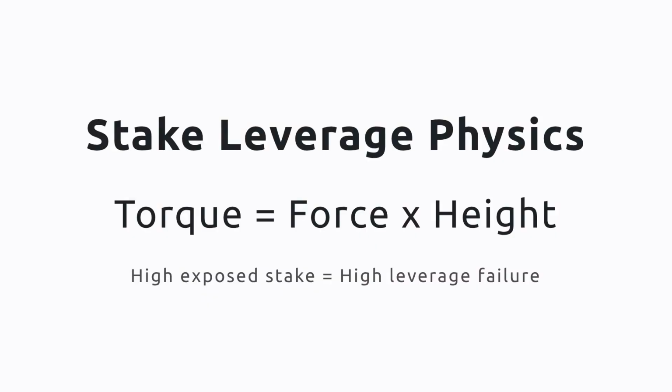Finally, consider soil mechanics. A stake's holding power is roughly proportional to the square of its depth. Driving a 6-inch stake only 3 inches deep creates a lever arm that magnifies the extraction force. Full insertion is a non-negotiable safety margin.